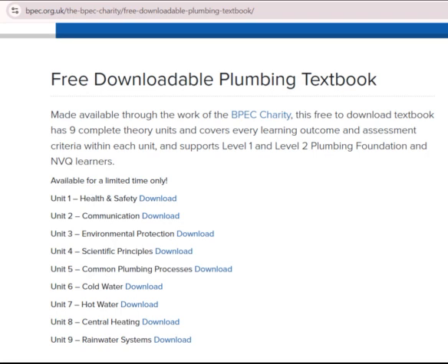Relative density, specific gravity, to air. The relative density of a gas is better known as specific gravity, SG. The specific gravity of a gas is measured against a known gas. This gas is air and it is measured as 1. This means that any gas that is lighter than air, such as natural gas, helium and hydrogen, will have specific gravities less than 1, and any gas that is heavier than air, such as propane and butane, will have specific gravities greater than 1. The table below shows the specific gravities of some common gases.